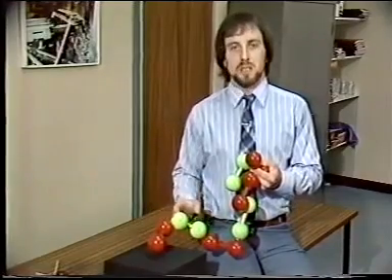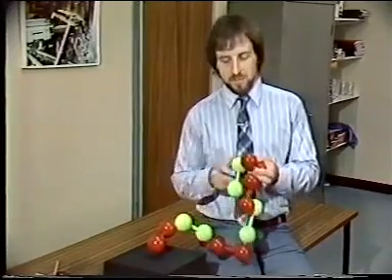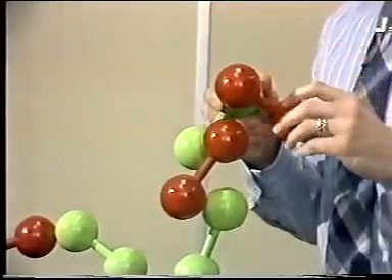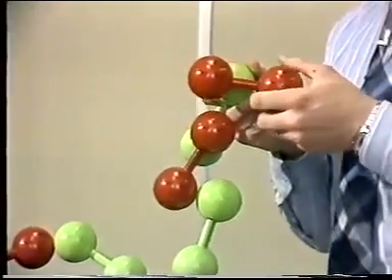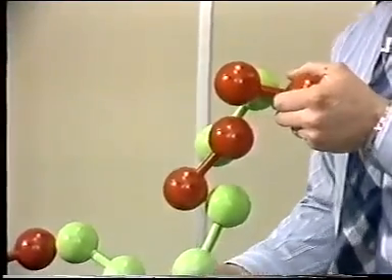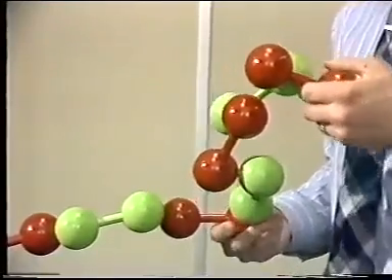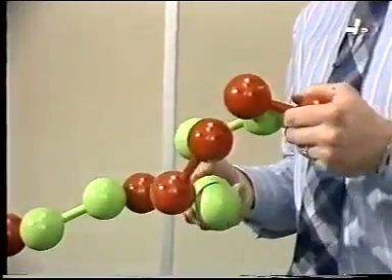There are 7 links, which are these dumbbell shapes, interconnected by 6 revolute pairs. Its interchange graph therefore has 7 vertices connected in a simple chain by 6 edges, marked with R to represent the fact that they're revolute pairs. This end link, or gripper, as it would be in a manipulator, has 6 degrees of freedom.